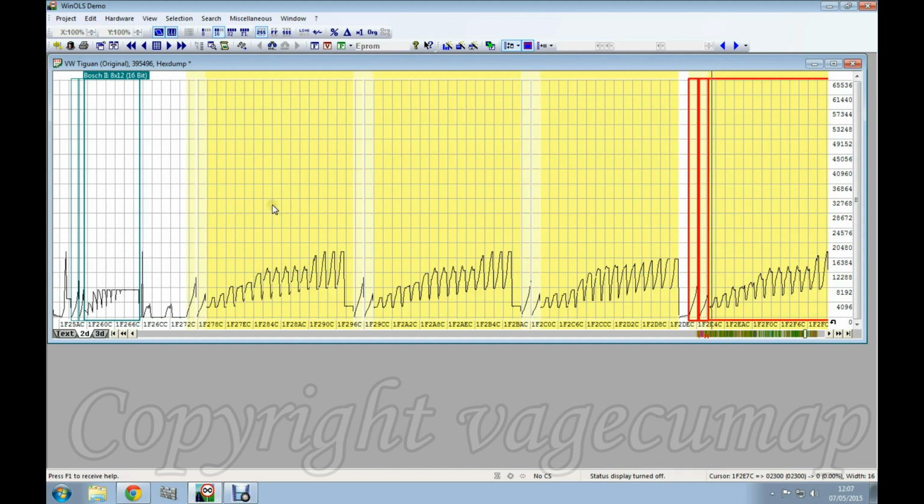It's not surprising. Sometimes there will only be one because there's just one map and that's it, or sometimes there's multiples but the difference between them is not very much, or sometimes you might get perhaps just 2 sets of maps and one is for normal running and one is for regeneration, that sort of thing. But basically that's what they're there for. They're determining the amount of pressure that's going to be in the fuel rail.